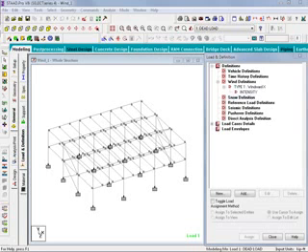To complete my wind definitions for my wind load in my global x-axis direction, I should now also create a wind definition for my leeward wall and my side walls. To do this, I'm going to follow the same exact process I did for the windward wall, except I'm going to specify the different walls of the structure when I get to the design pressures section. So let's begin with our leeward wall.